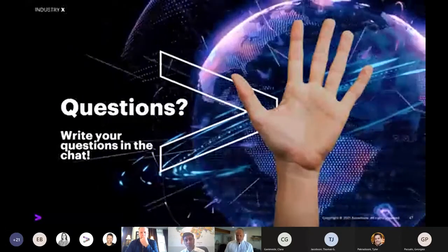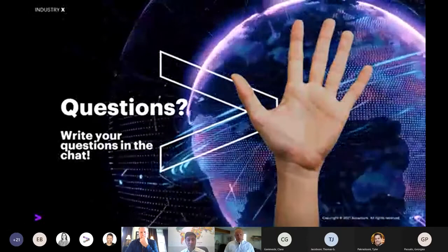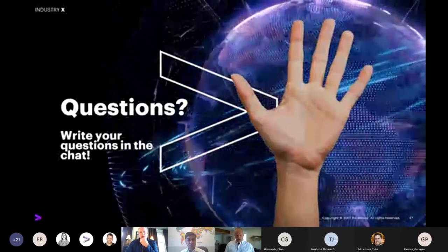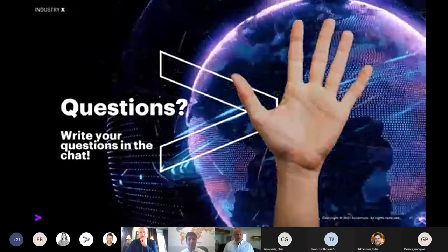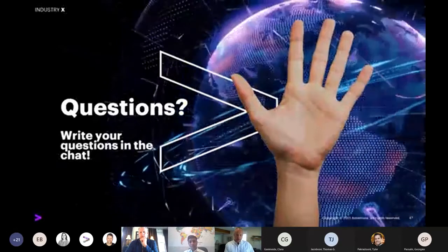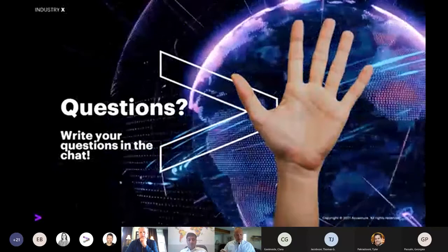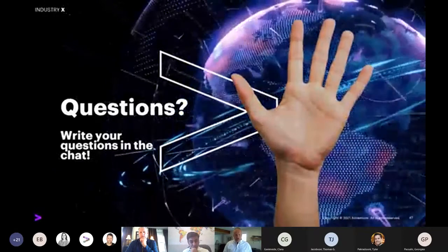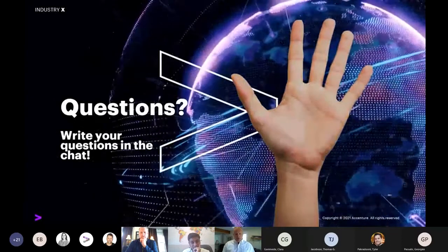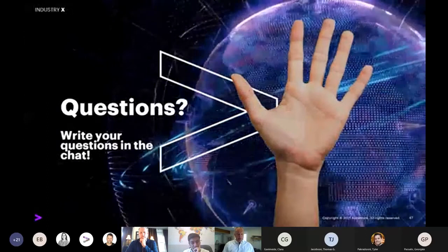Absolutely, Russ. Happy to. So it starts with a digital definition. And the richer that definition is, the more insights we can bring. So we saw a CAD model there. That's great. If that CAD model has tolerances on it, that's even more helpful, because that's going to dictate what we're going to call digital simulation. So we start with all the information we can, and then we analyze the model, and we call them basically cost drivers. So if it's a hole, or if it's a plastic part, or it's a machine part, sheet metal stamped, we analyze what it's going to take mechanistically to make that part.